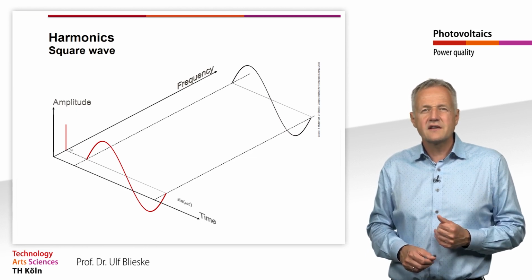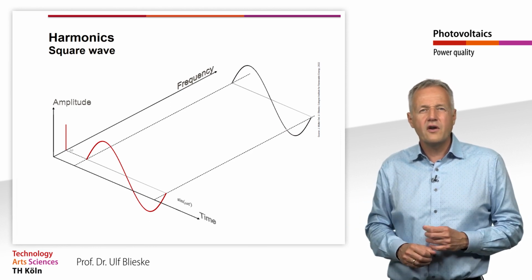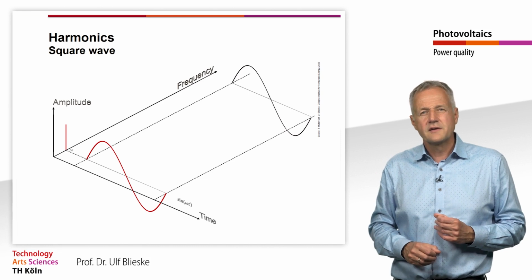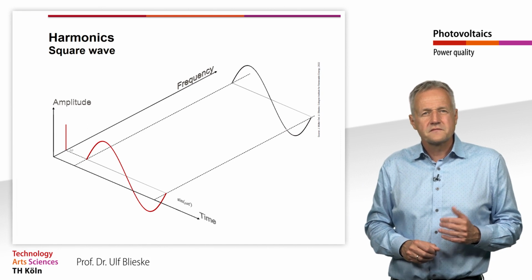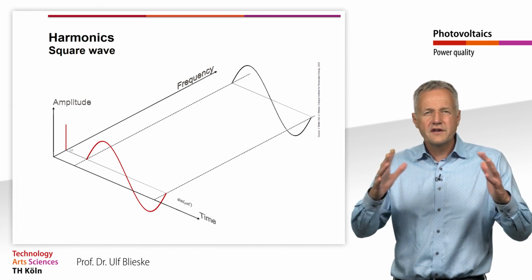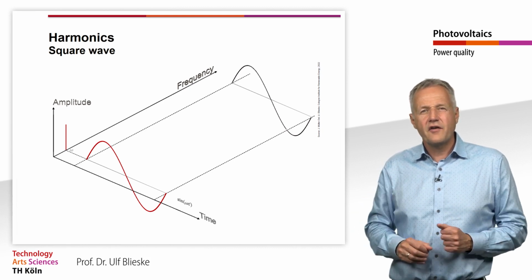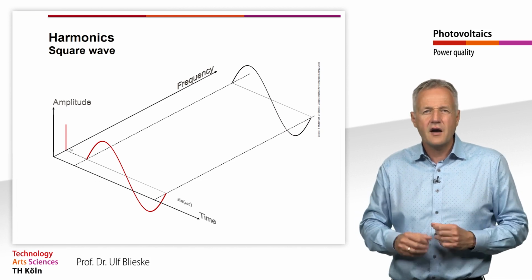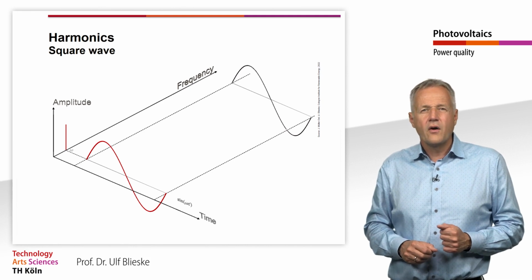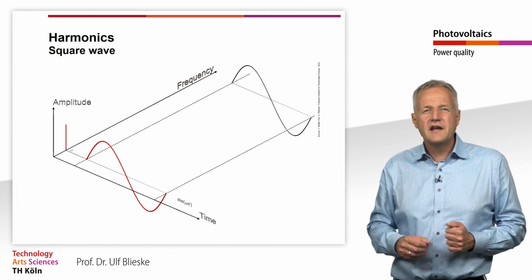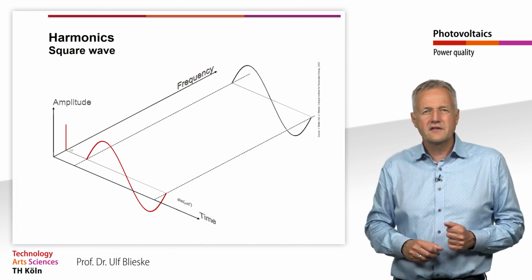As just briefly explained, the actual shape of an alternating current usually deviates more or less from an ideal sinusoid. This is also called a distorted sine wave. With the help of the so-called Fourier analysis, every periodic signal can be decomposed into a fundamental wave and various harmonics, also that of a distorted sine wave. Or expressed the other way around, any periodic function can be composed of a fundamental wave and various harmonics.